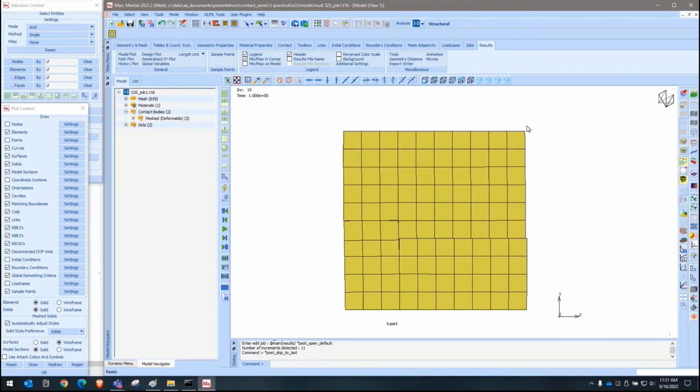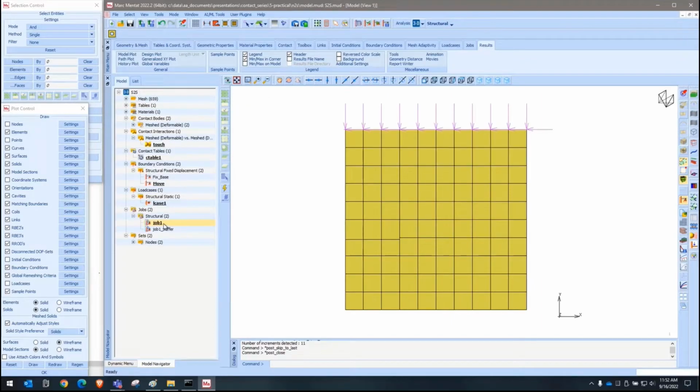If instead of enforced motion, I applied a load there, whatever load I've applied there will be transferred to this. So the exact distribution may be slightly wrong if the stiffness is not enough, but it will be pretty good still. If I apply an enforced motion and the stiffness is not enough, so let's do a model of that.